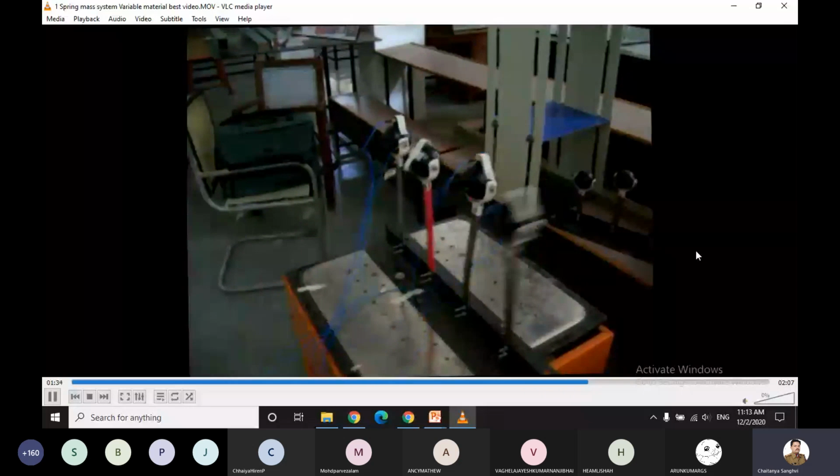This is a very classical example to understand the resonance, right? Now if I increase the frequency, again the first two models are not responding. Now the third model starts responding because it has a higher frequency. I increase the frequency of shaking until it matches the frequency of this model, and therefore, look at this, in resonance you get an enlarged response, right? Now still I'm increasing the frequency. Now look at the behavior of the fourth one. Again I'm repeating, the same motion is applied to all, right?